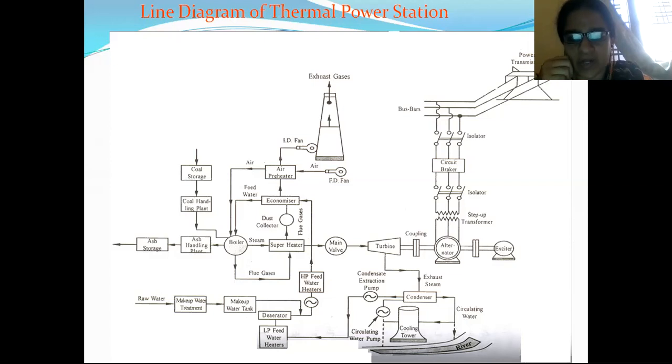Right, what the superheater does is, it increases the temperature of the steam which is coming from the boiler. This superheater is connected to the main valve. After that, the main valve is connected to the turbine. What this turbine does is, whenever the steam energy is given to the turbine, this turbine is the device which will convert steam energy, or heat energy, into mechanical energy. The turbine has blades in different directions.